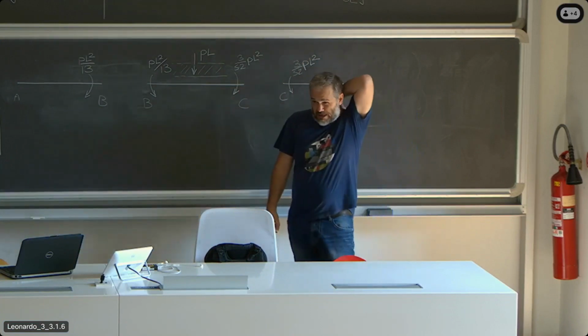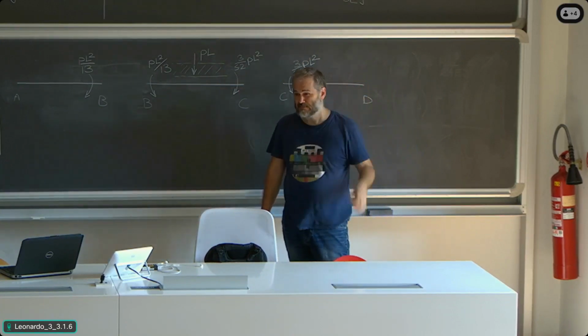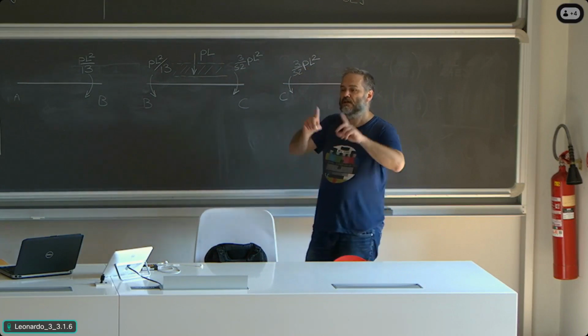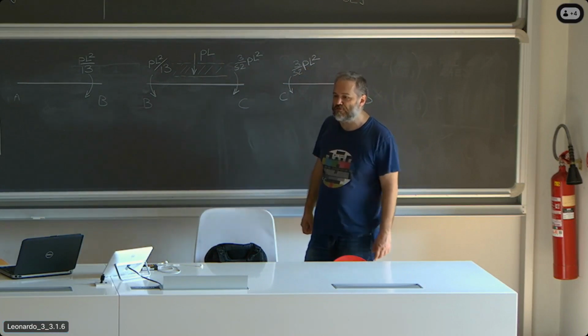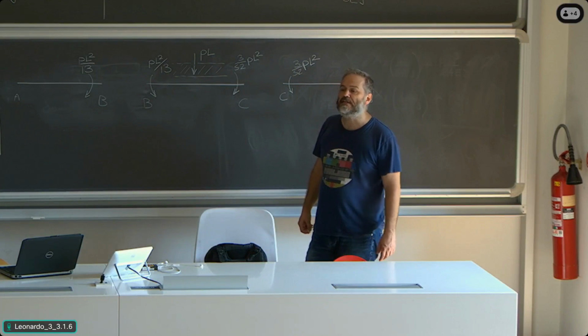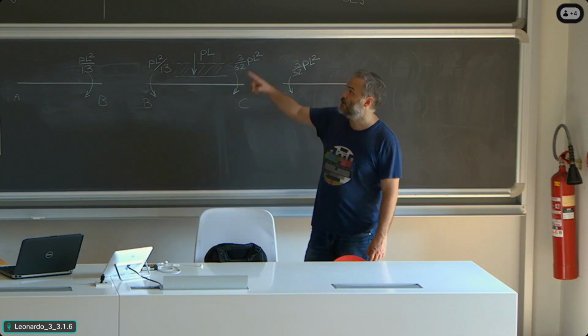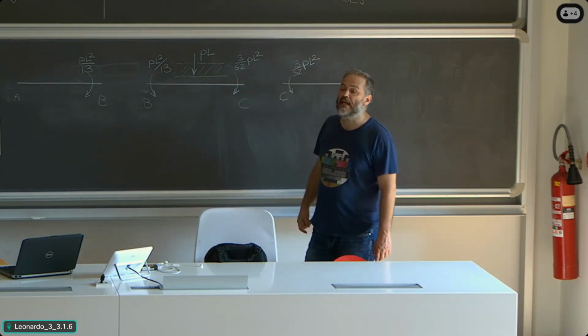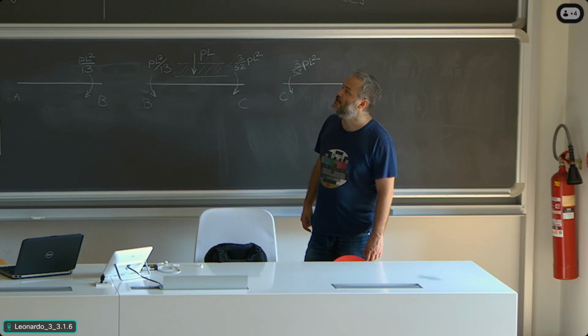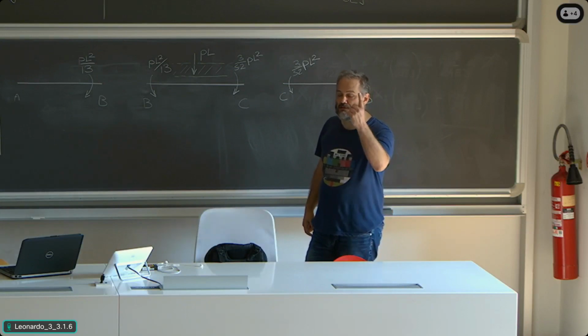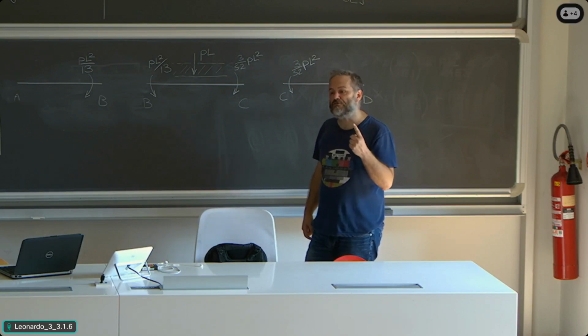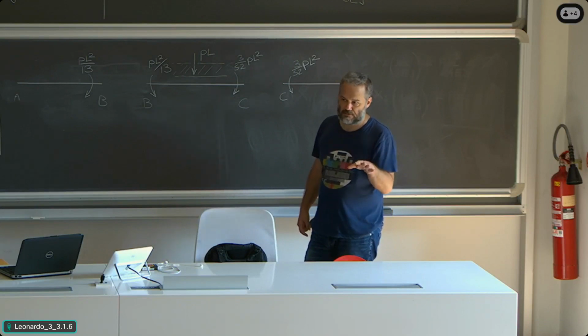What do we have to work out? Let's start with the end forces, which are shear forces. I will not look at the axial force. Why? Because, as it is usually the case, if you look at the situation of our beam, we have basically no horizontal loads applied, just one horizontal restraint, which means the horizontal reaction force will be 0.